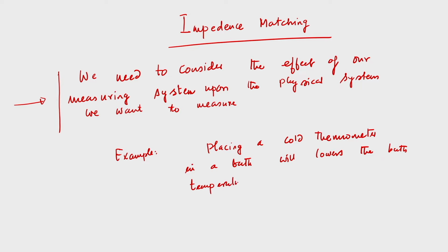That is very important: if we would like to measure the temperature of a liquid in a bath using a thermometer, and the thermometer we are going to consider for that measurement is cold, then obviously it will lower the temperature.